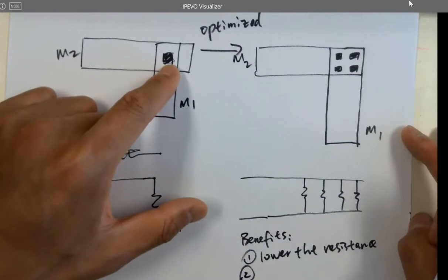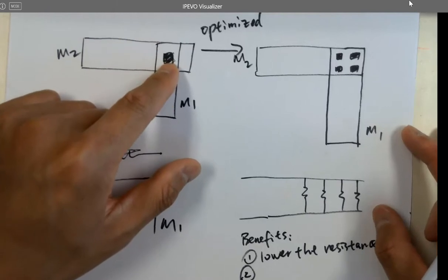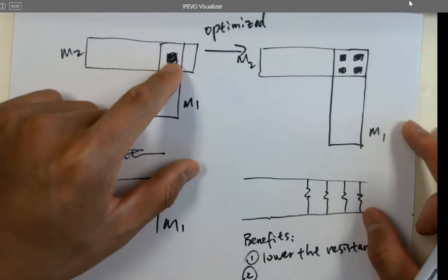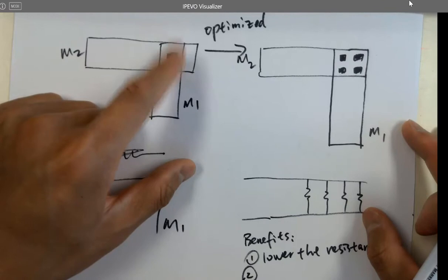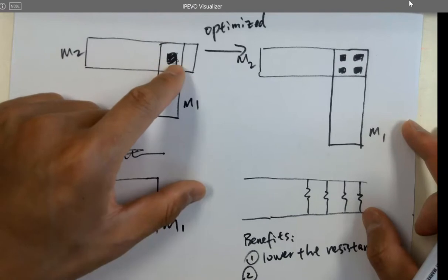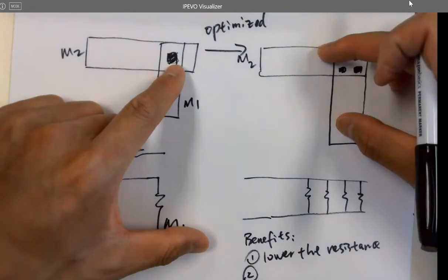Not wire straight. This one you have wire. Oh, increase resistance. Yeah, these are not resistors. These are just the vias. Because they are super tiny. You can imagine in the 20 nanometer technology, the vias are probably at the nanometer level. So the resistance can be pretty high, right? And what's the second one? So lower the resistance, to keep them at the same potential, right?